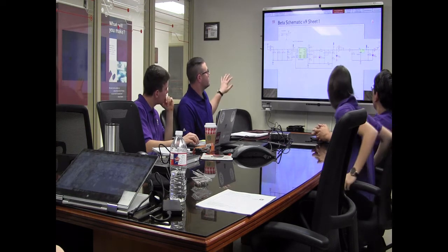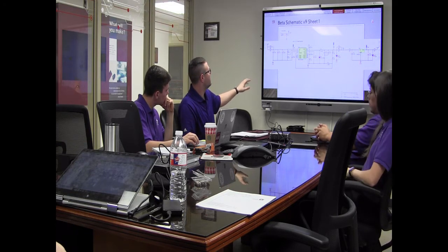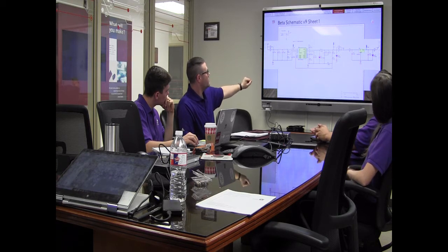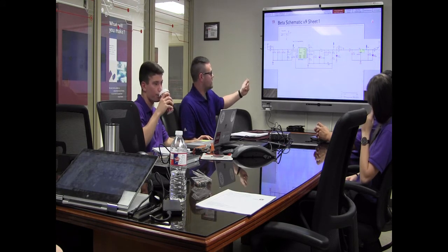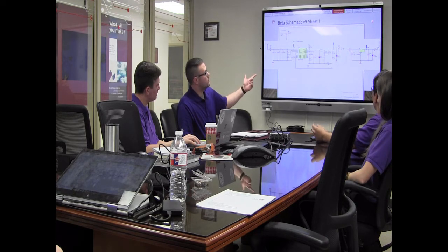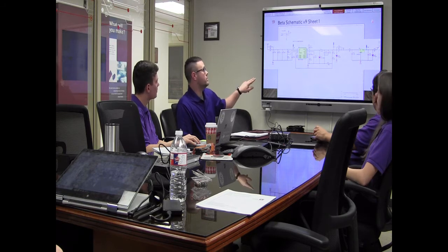And here's one of our main 12 volt to 5.5 volt voltage regulators. Kind of key features are the 0 ohm resistors on the front half, lots of decoupling, a little bit of sense lines. And this is straight out of the data sheet, out of the reference design from TI. It's a TPS54531DDA. It's rated for 5 volts and 5 amps. It's got a little indicator LED that's 5 volt tolerant. How many of those LEDs have internal resistors? That one does. Actually, both of them do.